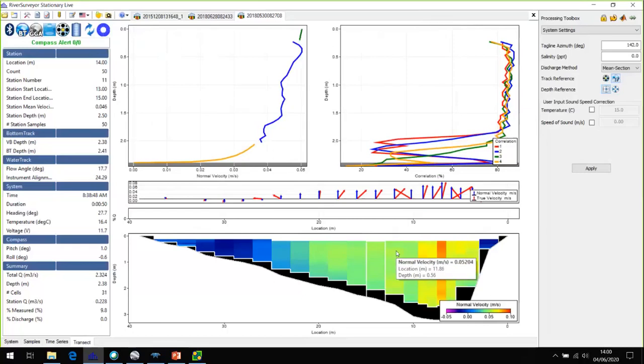There is, as I was saying, a very good call here for moving location. Now with the RQ pods or the ARC boat and the extra capability of GPS stationary, I would go downstream and do a GPS stationary down there, which I do fairly often now, rather than this location. I've got data, but it's not the best data I could possibly get, so I can get better data downstream where the river's shallower and flowing a bit better, even though I don't have a cableway there. I still wouldn't use moving boat. That's the point. I would go back to stationary there.